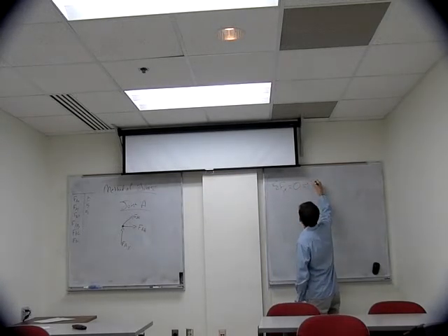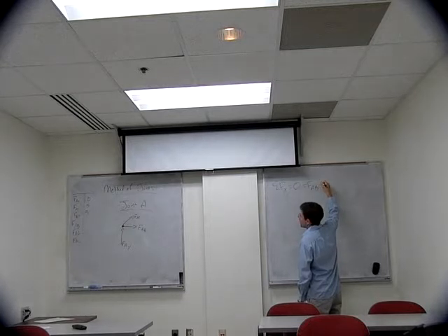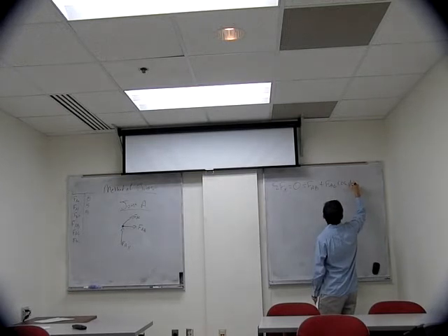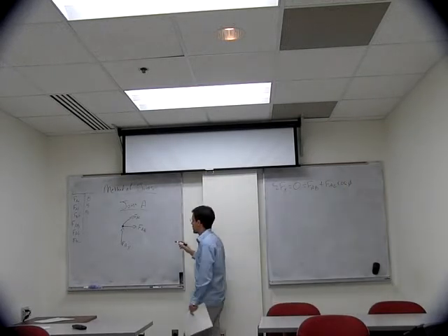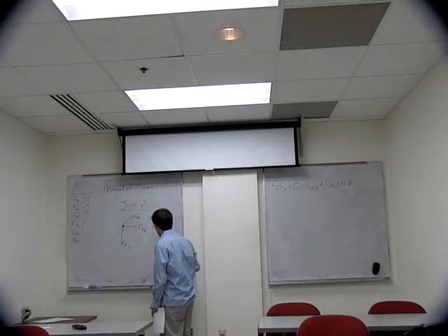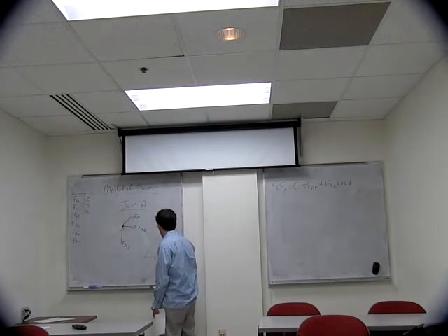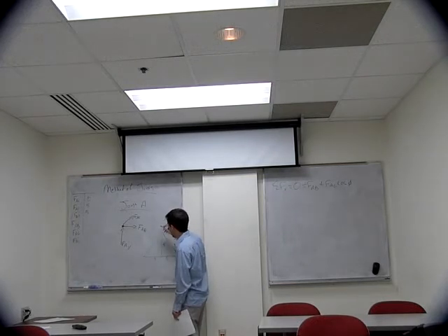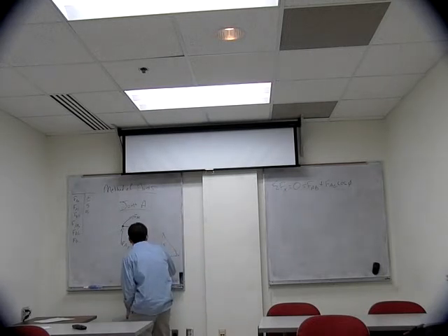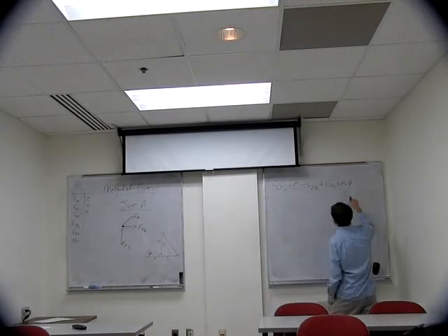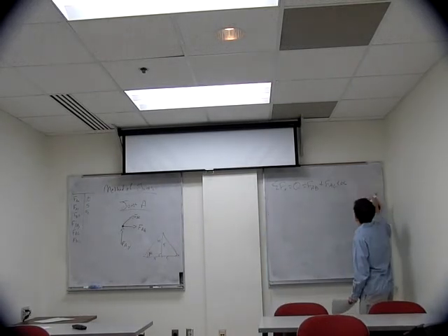So here we have Fab plus Fac times the cosine of our angle. And we know that our angle is going to be 45 degrees if you look at the initial setup. So this is 5. We said the height was 5. So this is just a 45, 45, 90 triangle. So we know that our angle here is going to be 45 degrees.